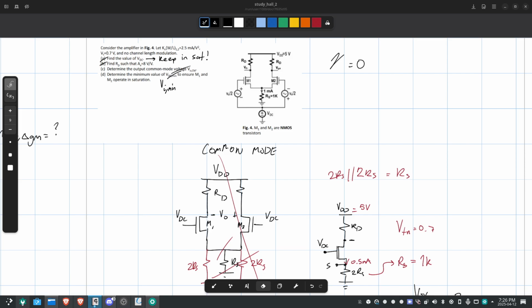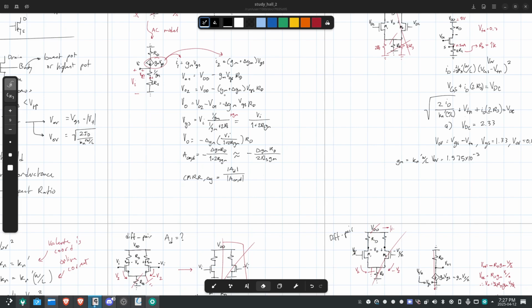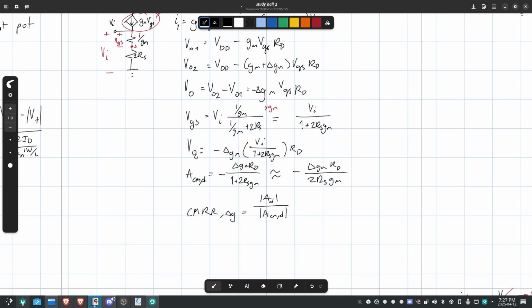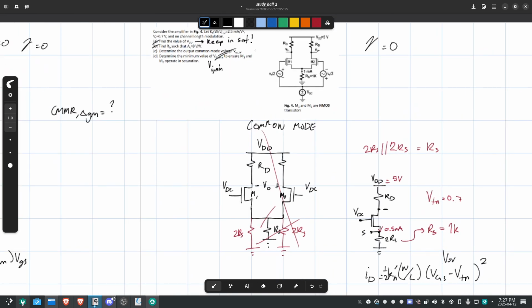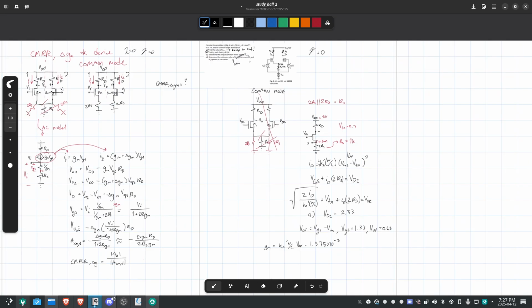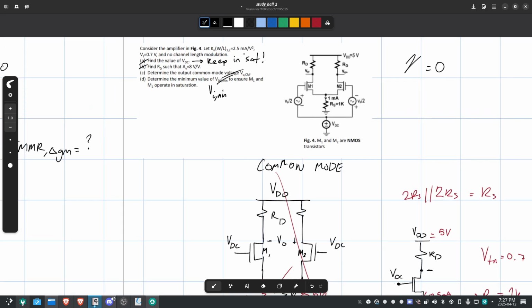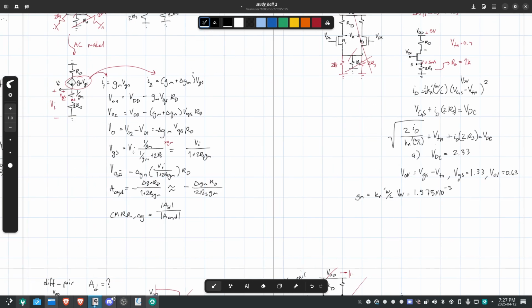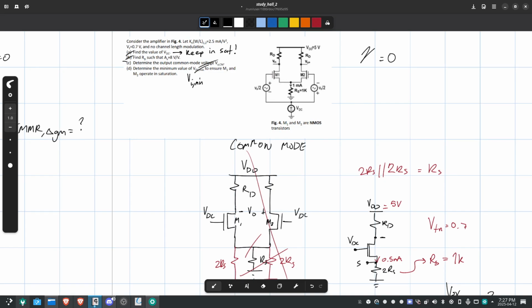No, I didn't, because the common mode voltage, it's the same process as I did the first question here. That would just be this one here, the common mode output voltage. Just turn this into CM. I believe it's also single-sided then. They would want a single-sided one, because if it's not, then it's kind of useless. So here, all this is saying is find VO1 at VDC, because that would be the VO1 common mode single-ended.